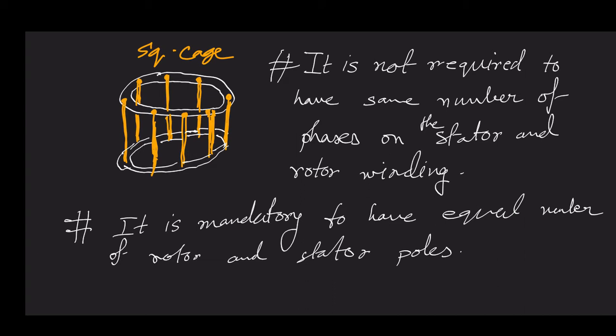Now you can take out the rotor if you find the rotor circuit is healthy and intact, and if the rotor matches the mechanical dimension of another stator having 6 pole, 8 pole or 10 pole, you can easily place this rotor, which initially was installed inside a 4 pole machine, inside a machine that is having 6 pole, 8 pole or 10 pole. You can easily place it there. There will be no harm, no confusion.